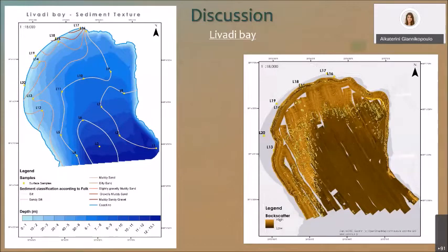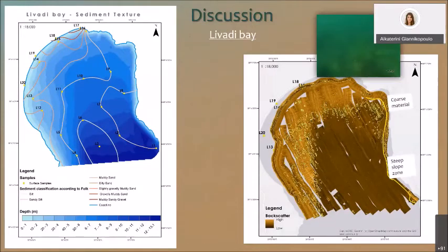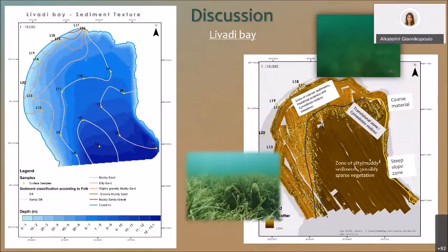On the side-scan imagery, there are portions of steep slopes and coarse material visible to the east, and a mild local topographic depression along the northwestern coastline. In the deeper part of the bay, a large area of fine-grained sediments is visible. A large zone of marine vegetation meadows is identified at the shallows, followed by a transitional zone featuring sparse vegetation on fine-grained sediment.